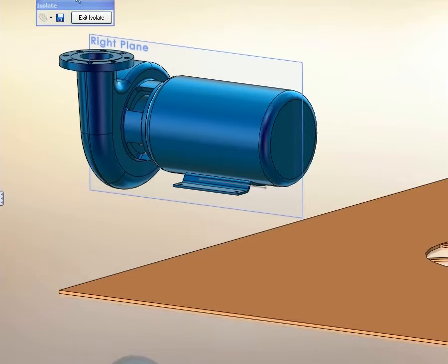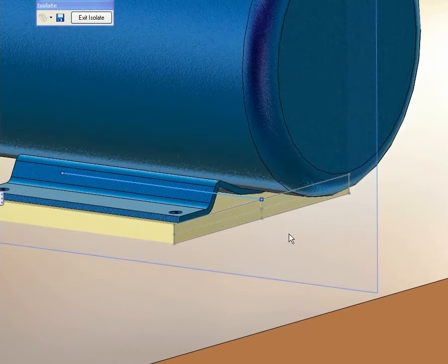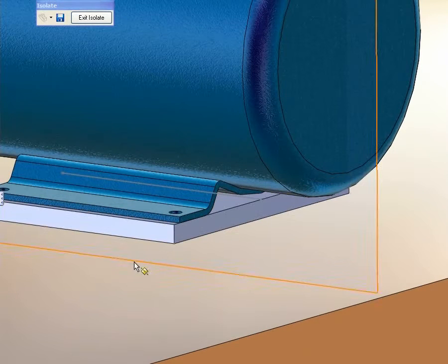To do this, we'll use the weldment tools. Notice the various libraries that we have. In this case, we're going to choose plates. We'll also choose the thickness. We'll choose 3/4 inch thick, and then we'll choose a width. For this case, we don't really know the width yet. We'll just choose 12. We can always change it down the road. SolidWorks gives us a nice preview of what our plate's going to look like. We'll go ahead and accept that.